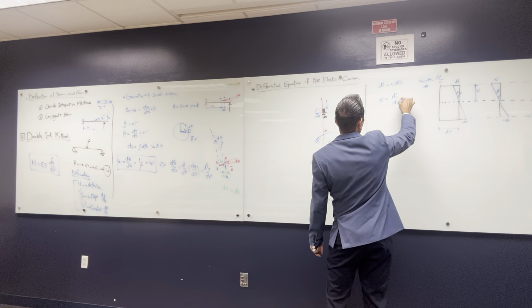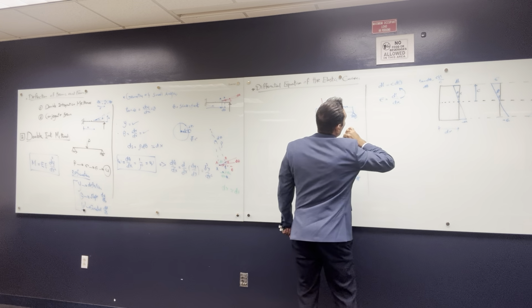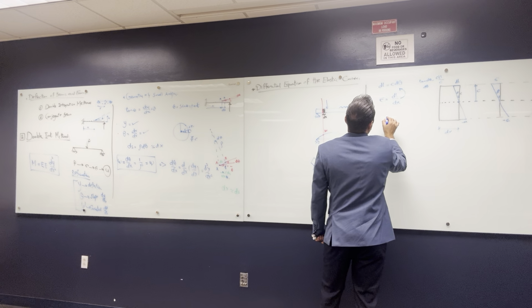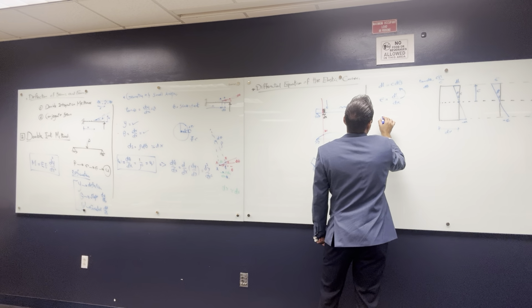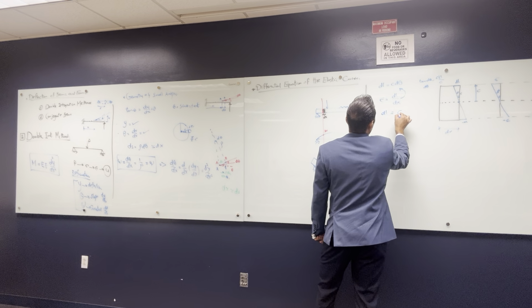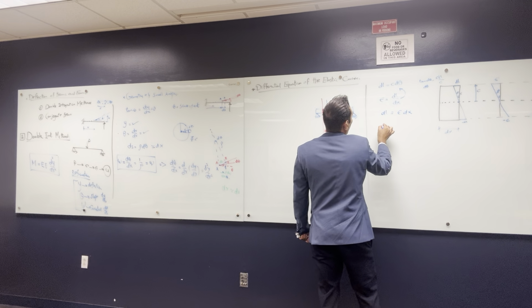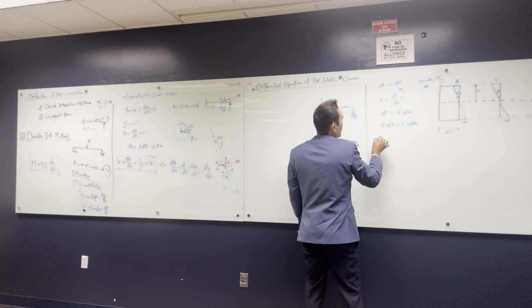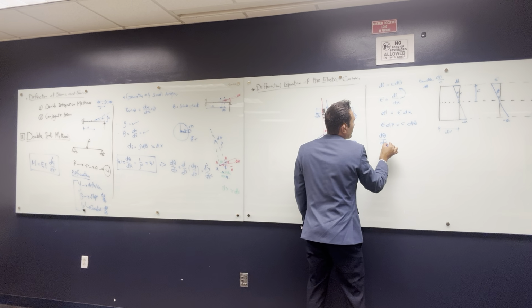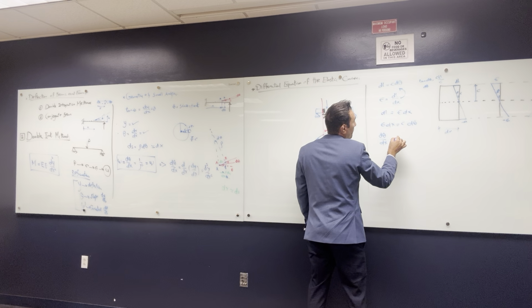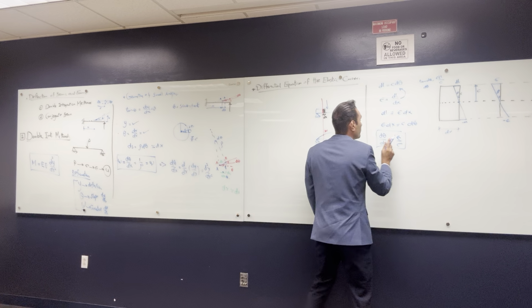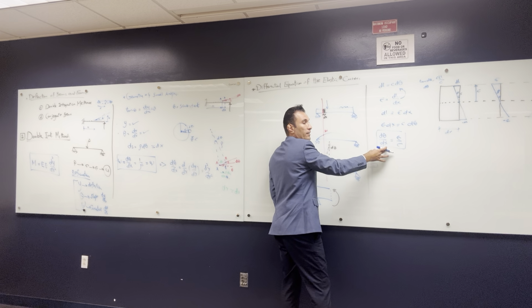So if we want to substitute here and get this one here, like removing this, dl is equal to epsilon dx. So epsilon dx is gonna be equal to c d theta. So if you want to find d theta over dx, it is gonna be equal to epsilon over c. That's the first equation that we need. And what is that? What is d theta by dx? That's the curvature, right?